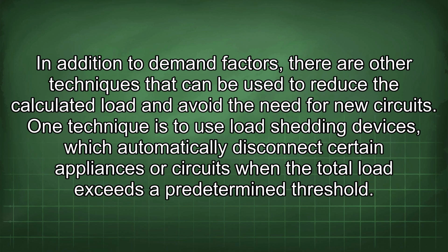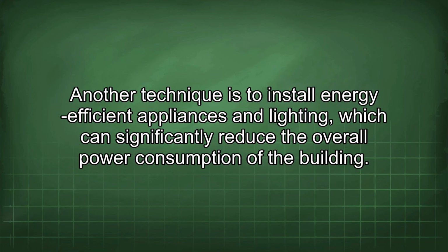In addition to demand factors, there are other techniques that can be used to reduce the calculated load and avoid the need for new circuits. One technique is to use load shedding devices, which automatically disconnect certain appliances or circuits when the total load exceeds a predetermined threshold. Another technique is to install energy-efficient appliances and lighting, which can significantly reduce the overall power consumption